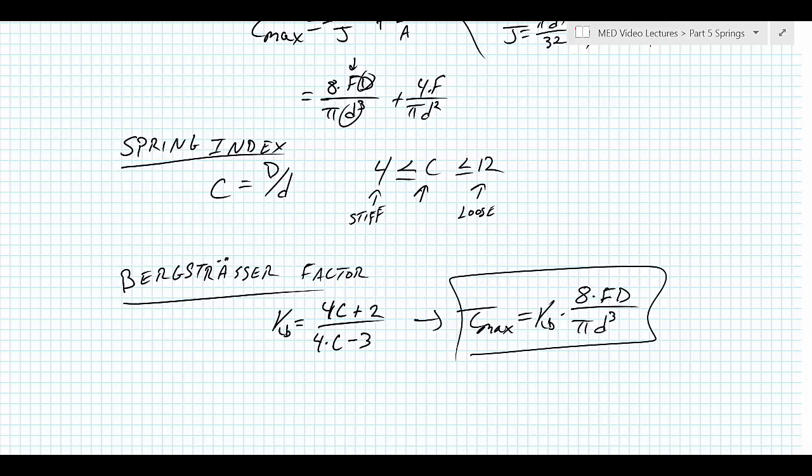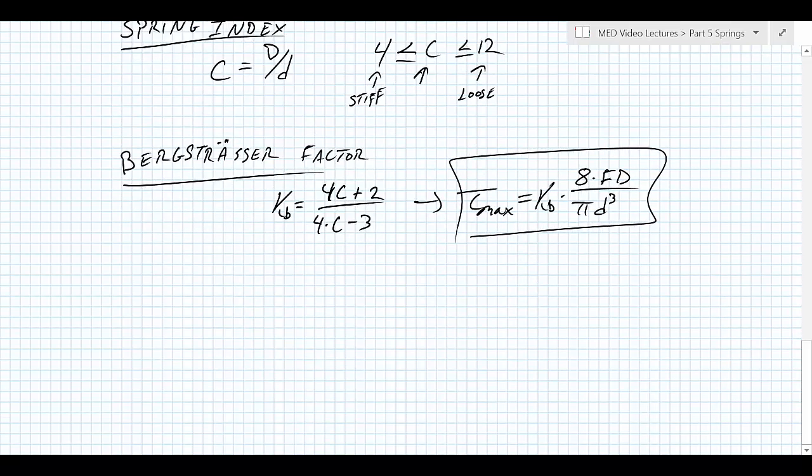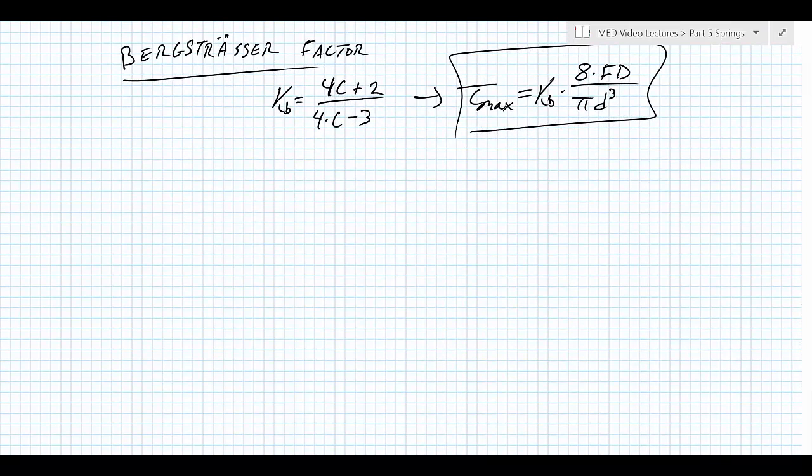So now we could go ahead, if we wanted to, and we've got shear stress, so we'll have a pure shear type of case. We can apply the appropriate yield factors of safety, such as maximum shear stress theory, and we can apply our fatigue failure theories and say whether this spring is going to fail in yield or fatigue or not. Which is great, but it's not the only thing that we care about with springs. So what I want to do with the rest of this is talk about the other things that we care about with springs.